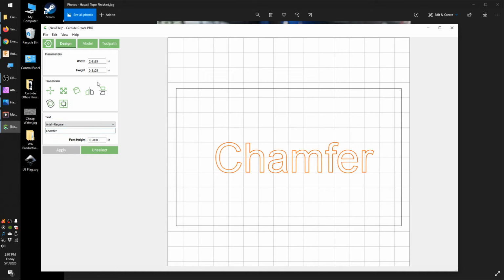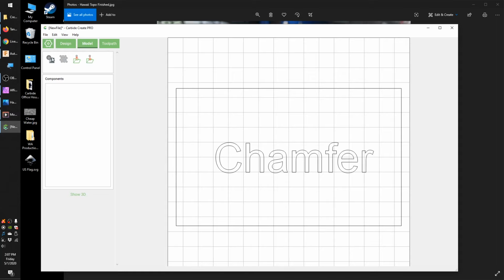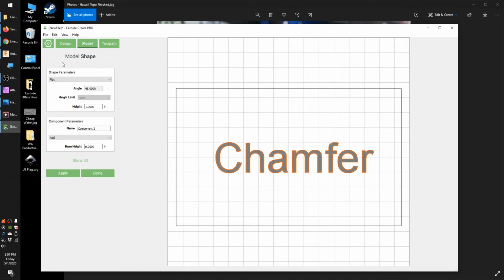And then let's try and extrude this upward with an angled constraint around the border. Maximum height of 0.02, maybe, with height limit enabled and a base height of 0.1. Let's see what that looks like.